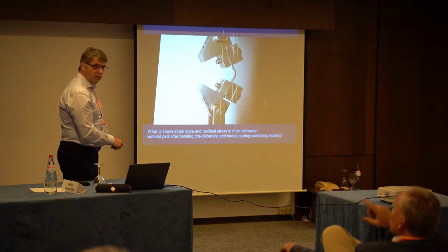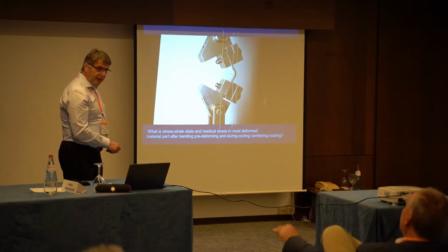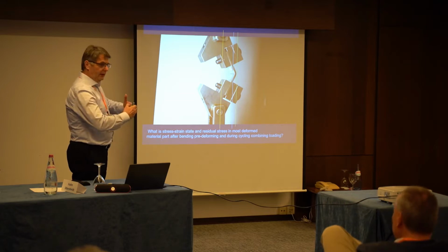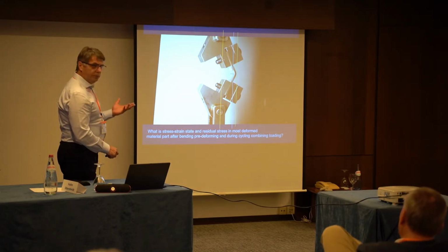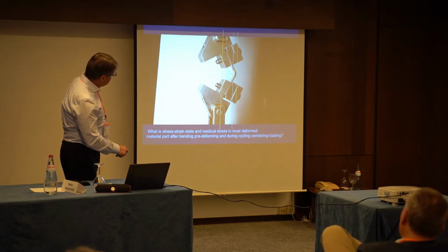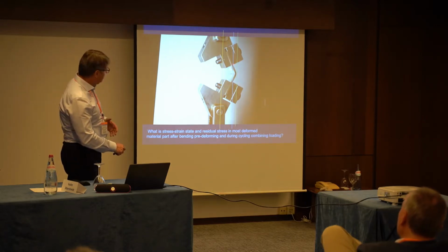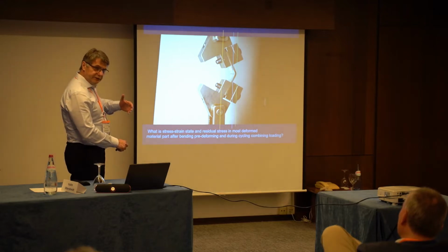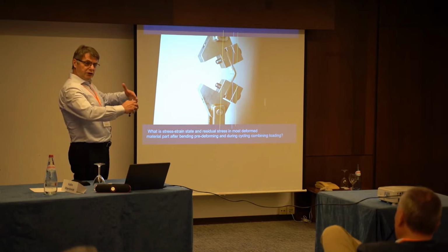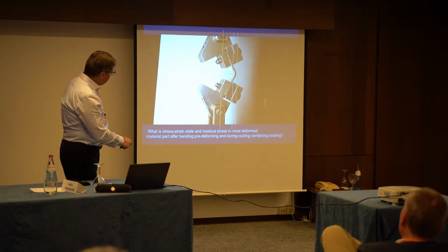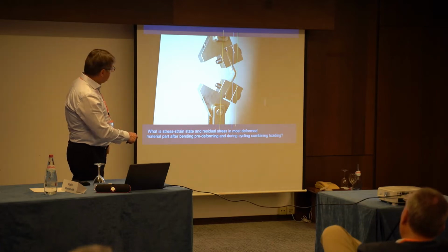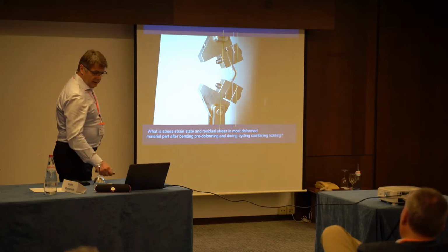And now it was pre-bent, yes? Yes, it was pre-bent. Pre-bent, and then you start doing this, and then we try to open it. It will now be possible to see the movie. You will see that this part, where it's martensitic structure, has a different stiffness, and then you will have non-uniform deformation. It will not open like that. The martensite remains here because you have no martensite on this side.